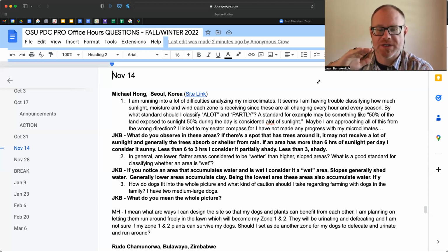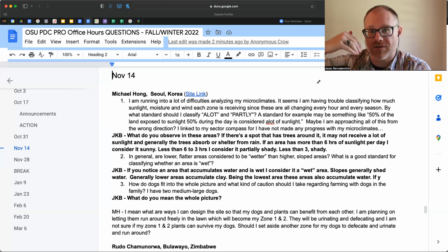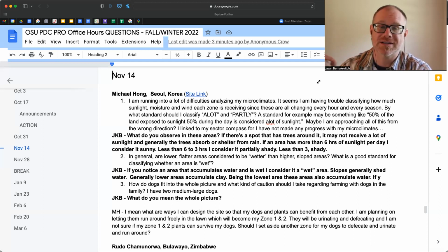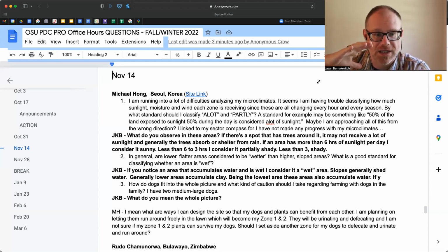And this is why when we're taking a look at convex to concave areas within our landscapes, generally we're going to find clay, because what'll settle out first is the sand, then the silt, and then the clay, being the smallest and the lightest particle, the sand being the largest and the heaviest particle. So when we have low-lying areas, generally if they're micro, let's say in an urban landscape, or macro in an acreage or on large stations, what'll happen is those areas will be low-lying and they'll have clay. And so they're low and they have clay and they tend to hold water.